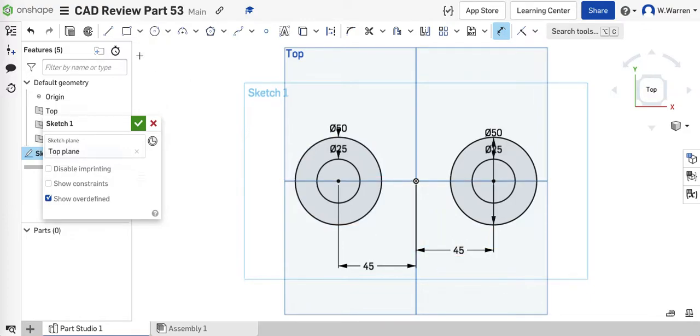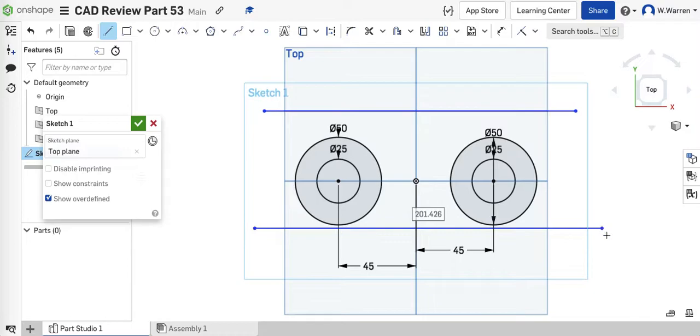Okay, next thing I'm going to do is grab a straight line tool and just draw a horizontal straight line that's too long. You can tell it's horizontal by the little horizontal line that shows up right underneath my cursor. See that? It's horizontal. If I go out of horizontal, that disappears. So that line is horizontal right there. It's too long, but we'll take care of that. And this one here, I want this horizontal too. Now, could I just have dragged those from here to here? Probably, but I would have no guarantee that they'd be tangent to the circle.